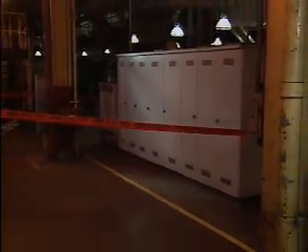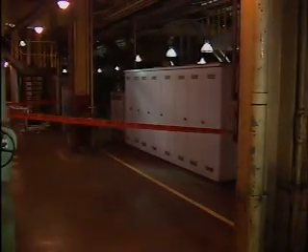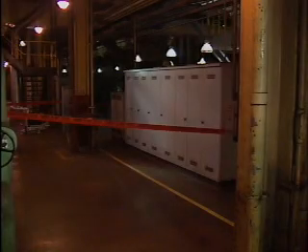Another aspect of performing electrical maintenance work safely is knowing minimum safe clearance distances. As part of the preparations for electrical maintenance work, temporary barriers should be set up to keep non-electricians at least 10 feet away from the work area.